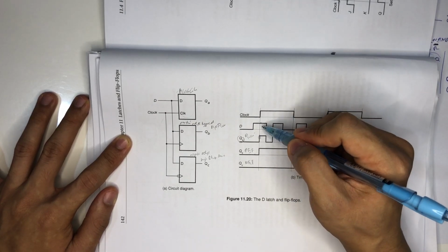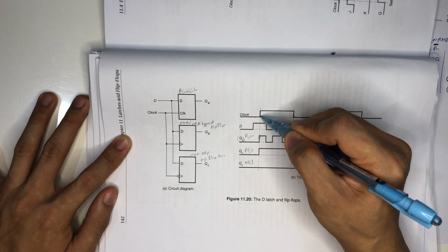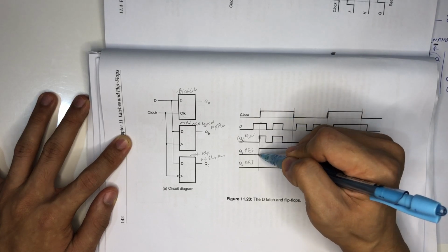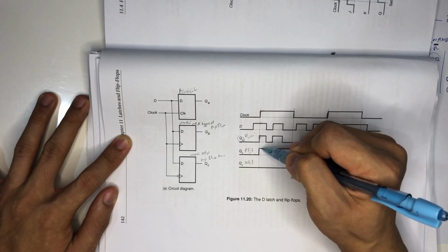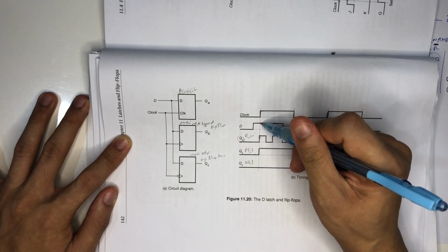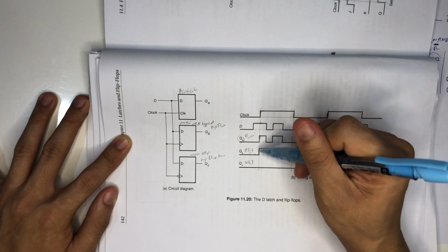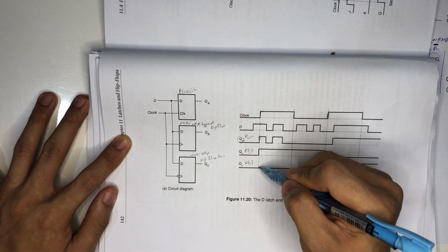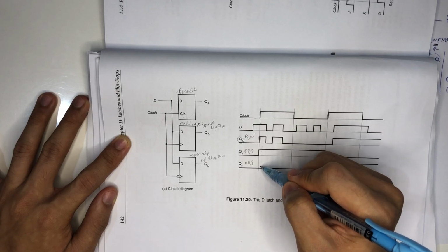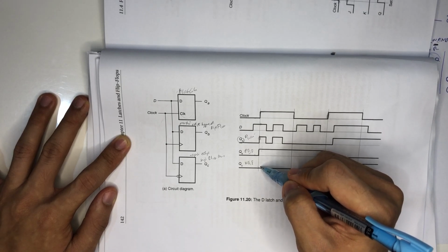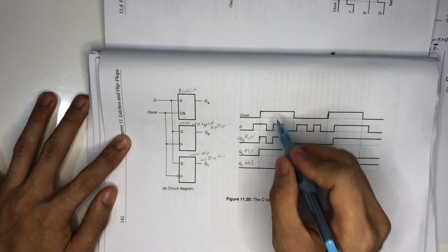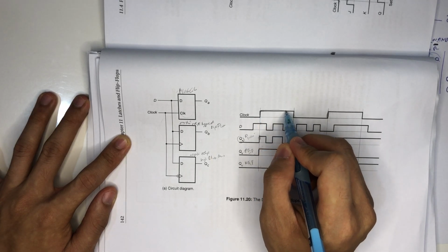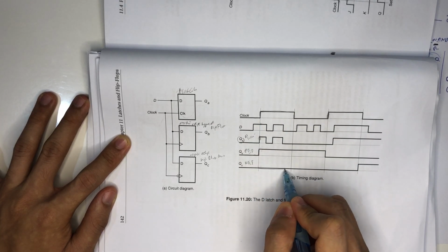So how about this positive edge trigger? When this one turns positive, the edge trigger will follow the previous input, which is the D. And what happens to the negative edge trigger? It doesn't have any changes, because it only responds to the negative edge trigger to consider the inputs. So during this positive edge trigger, your negative edge trigger doesn't do anything.